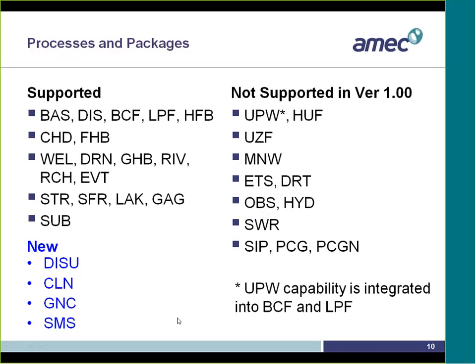New packages have come in. Instead of these solver packages of MODFLOW, now we have the new solver package, and it's just one solver package called the sparse matrix solver package. And within this are available several linear solver schemes. There are two essential linear solvers available within this, the PCG-U solver, written by Joe Hughes, and the Chi-MD solver, written by Mutsuo Ibaraki.